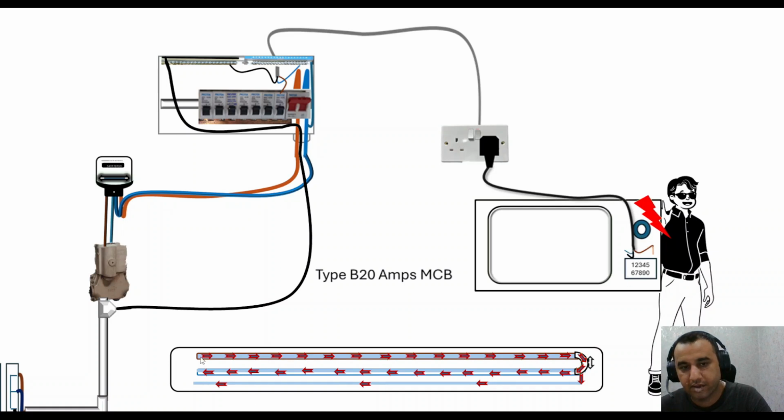The current is flowing, coming to this line conductor and going back through the neutral cable back to the system, but some of the current is leaking, and this leakage is going back to the system through this circuit protective conductor. So we've got a current coming to this microwave from the line conductor, but it's got two paths back to the system.